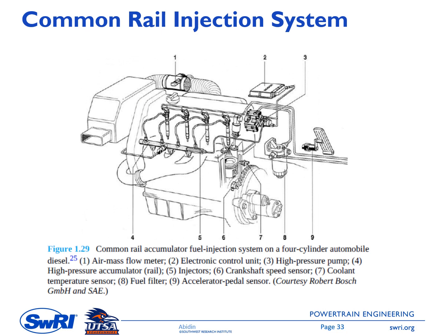And this is one of the injection system types. It's called a common rail injection system. You can see in here that each cylinder has one injector, and then there is one common rail here. With this common rail, it can ensure a good fuel distribution among the cylinders. So this is one of the new technologies for the diesel injection system.